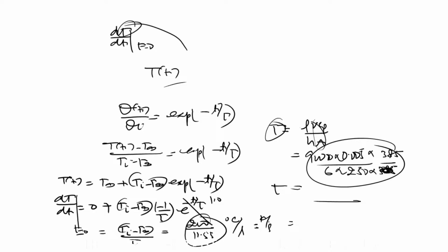Yes, Lc is the length scale corresponding to the maximum temperature difference. Otherwise, if the criterion is not 0.1, if the criterion is sometimes given as 0.4 like this, then you may take other values. In that condition, they have clearly mentioned on which basis they are giving the Biot number criterion. Like one question someone has asked me.